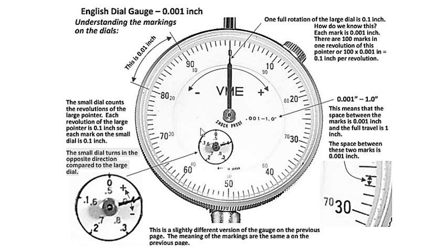I think you're going to struggle a little bit for the little dial. Let's just go in: 0, and then 0.1, 0.2, 0.3, 0.4, and then 0.5, 0.6, 0.7, 0.8, 0.9, and then go back to 1. So instead of 1, in order for us to make 10, which is actually 1 inch, you have to go 2 revolutions on that. This is how we read it.